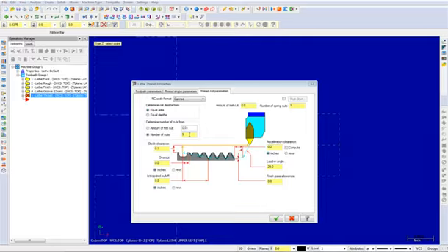For the Determine Number of Cut section, if you choose the amount of the first cut, Mastercam automatically calculates the number based on the amount of the last cut, the thread shape, and the depth of the thread. Stock clearance sets how far above the top of the stock the tool retracts between passes. Overcut sets how far past the end of the thread the tool moves before retracting. Anticipated pull-off sets the distance from the end of the thread that the tool begins to pull away from the thread. Acceleration clearance sets the necessary distance in the Z direction for the tool to accelerate to full speed before it starts cutting the thread.